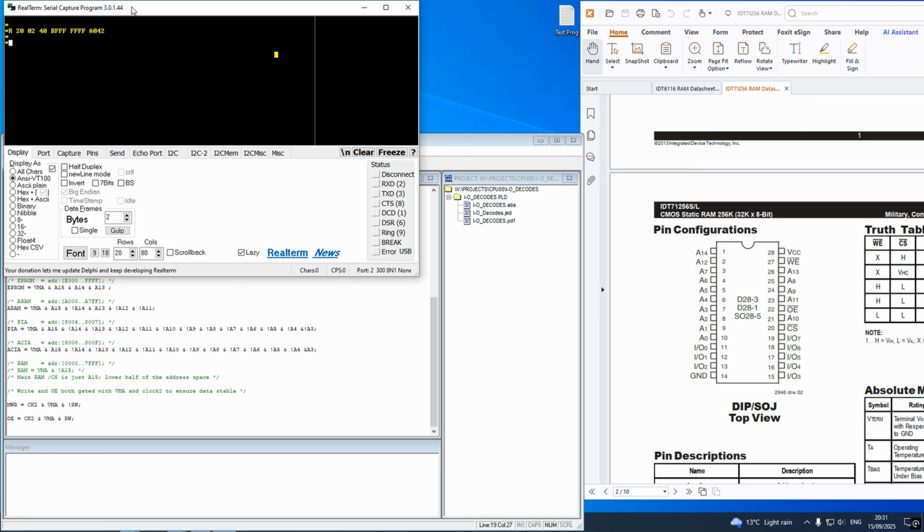Give it an R. We've got to put caps lock on. It doesn't understand lowercase. That ROM is very, very simple and primitive. So I've got the caps lock on, or else it just sees the wrong character. Give it an R, bit of a delay. It does a register dump.